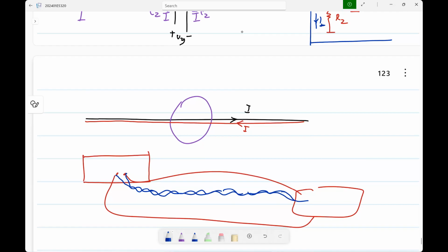That's why they make wires like this, in which one wire is basically inside the other. There is a shield and so on, so that it doesn't take in any magnetic field interference. So this is important, but anyway, in our case, this is just motivation for using fully differential circuits. And in general, all these problems get better if you make things smaller. That way ICs are anyway better, because everything is small, everything is compact. All this will become worse when you have physically larger connections and areas and so on.